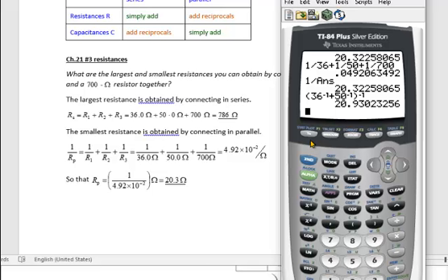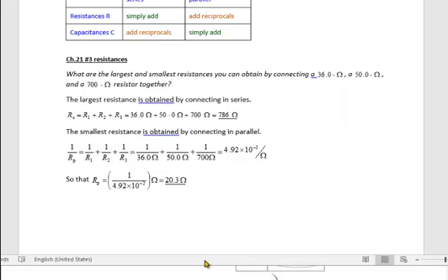So the 700 ohm resistor in the parallel circuit really hardly participates, which makes sense. There is that saying, an electric current chooses the path of least resistance. Well, if you already have 700 ohms, then it's going to rather flow through the 36 and the 50 ohms because they have a smaller resistance. Okay, anyway, let me go over to the PhET circuit.